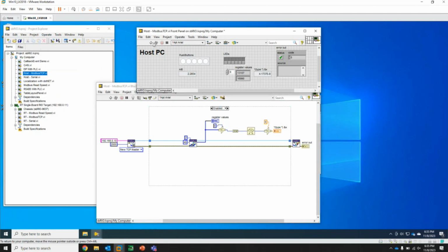Let's play the game of swap words. Here we go. But this particular typecast, if you go into the help, it'll show you that it does follow the IEEE standard when you're trying to convert between I32s and single precisions. If you do double, it abandons that whole concept. And same thing, if you have a single, you can straight typecast that into an I32, again if you're writing it back down to the PLC through Modbus.